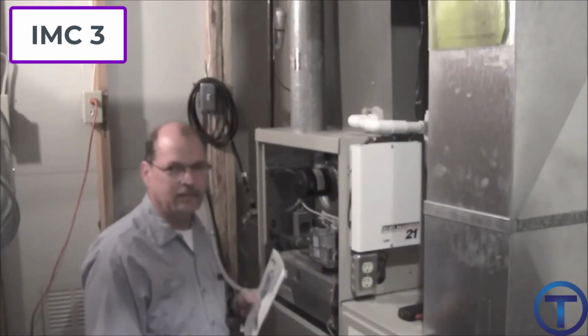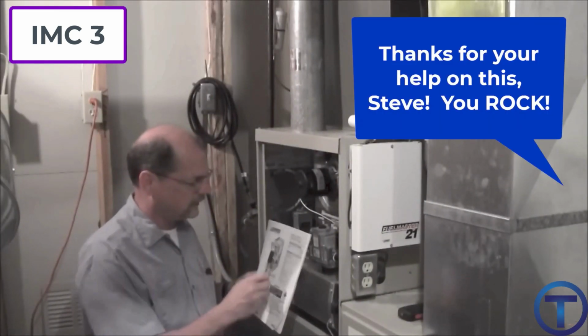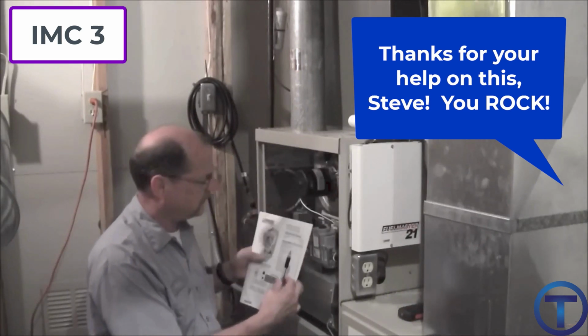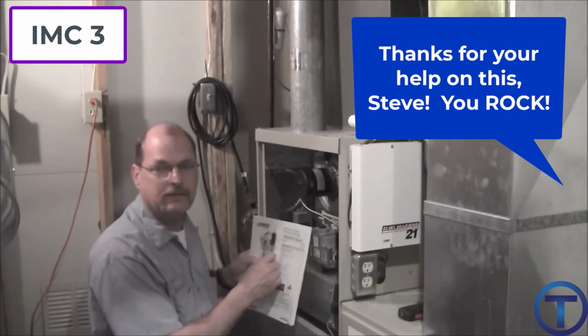Okay, so it may be best, now that we know where to find our model and serial number, to go ahead and jot them down on the front side of your installation manual. Now, how do I know that? Well, I do gas sizing, right? And anytime I do gas sizing, I have to go and find out all of the appliances that are involved in the building, and I have to go and look at them and get those BTU ratings if I'm going to make a change to the gas line. So I've dug into a lot of furnaces, and that's why I have this stance against that.